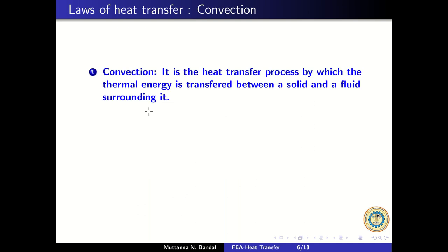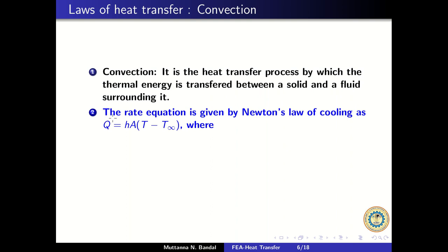Similarly, we can define convection as a heat transfer process by which thermal energy is transferred between a solid and the fluid surrounding it. Mathematically, the rate equation is given by Newton's law of cooling as Q = hA(T - T∞), where Q is the rate of heat flow, h is the convective heat transfer coefficient, which is a property of the medium, and A is the cross-section area of the exposed